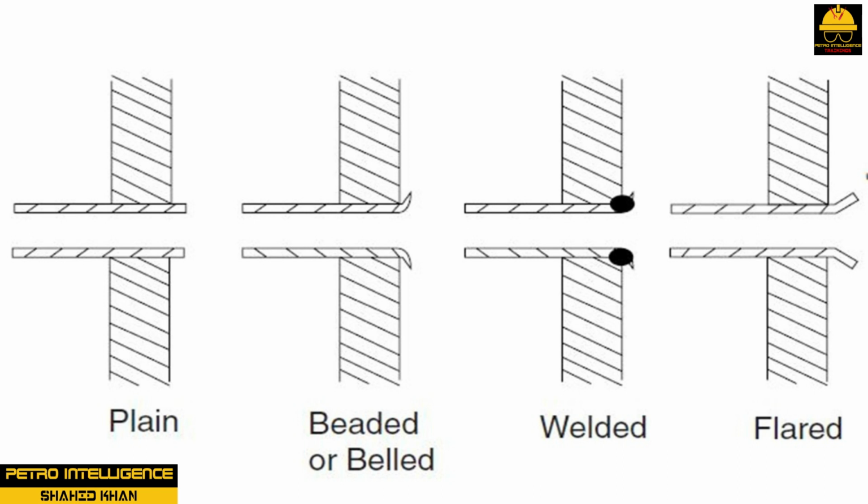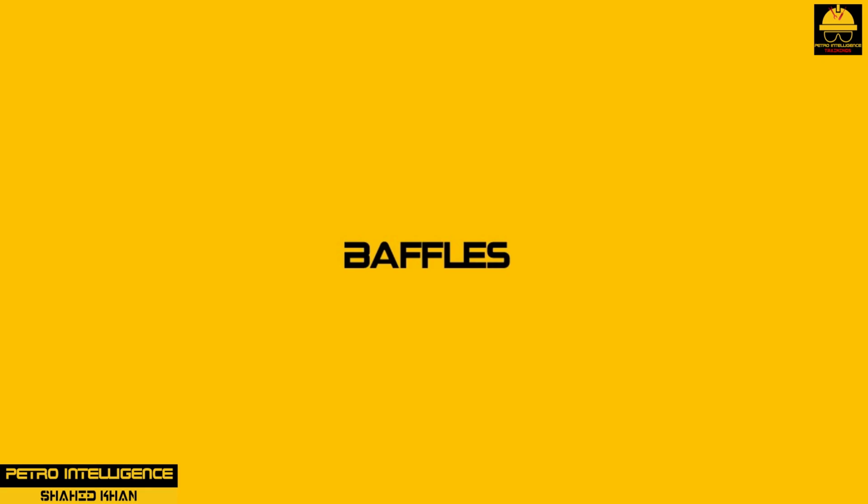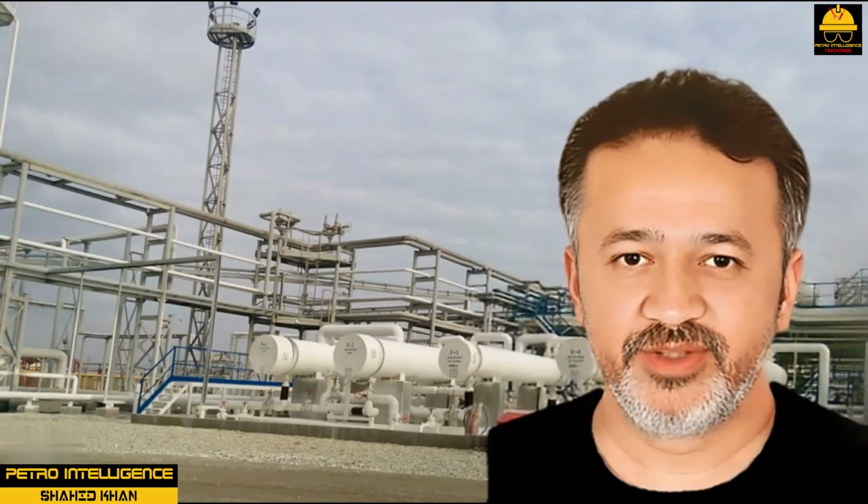During operation, the tubes will expand. This expansion creates a problem within a fixed head design. Engineering specifications take into account thermal tube expansion. The term fixed tube sheet applies to the way the tube sheet is located in the inlet or return head. If the tube sheet is welded or bolted to the shell, it is fixed. If the tube sheet is independently secured to the tube head and is allowed to move freely inside the shell, it is floating.